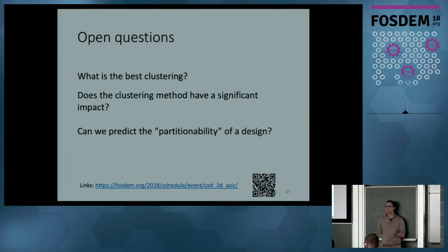Yeah, okay. You cannot yet do that because you would lack some 3D awareness in the flow. Designing your IC in 3D is the aim for the future, but in the near future we can't do that yet because we lack some tools to place and route, for example, in 3 dimensions. All the place and route tools are just 2 dimensions, X and Y. If you want a 3D-aware flow, you would need to add one set of coordinates to the place and route, and that is not done yet. So no, you still need to design it in 2D and then split it.